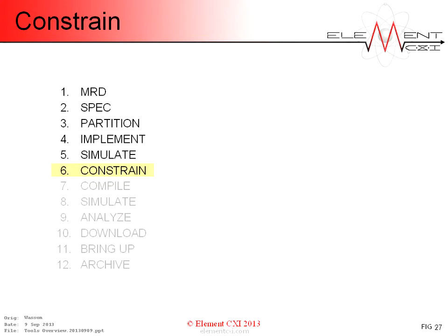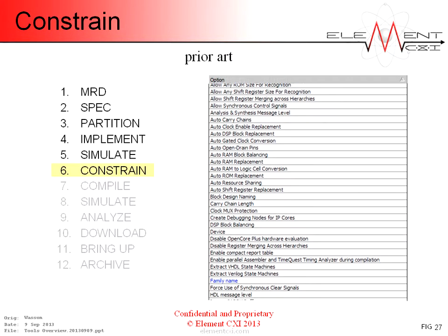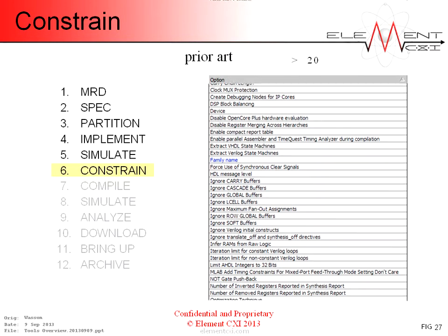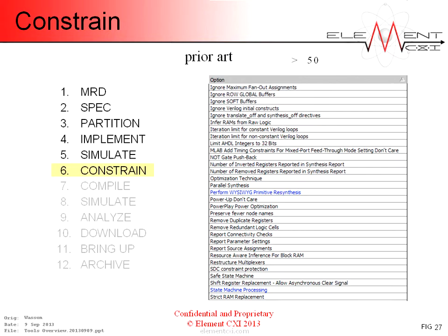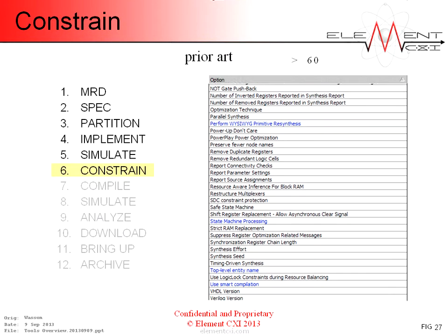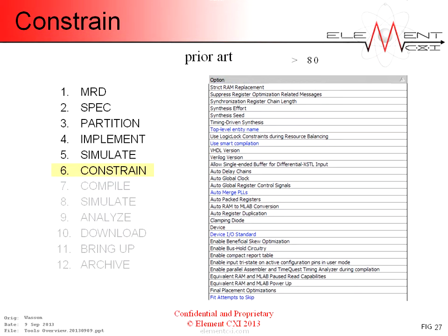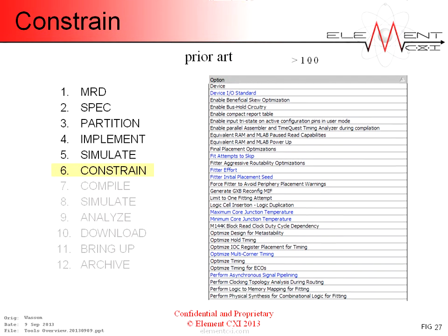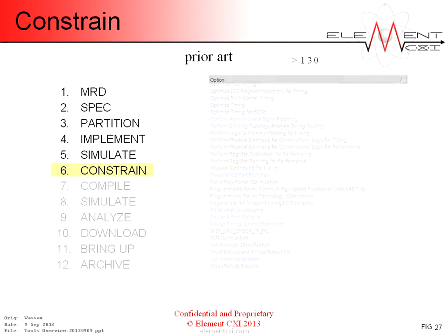Constraints in the real FPGA world have gotten, shall we say, complicated, as this list of Altera constraint options attests. There are options for anything and everything, and things you didn't know you needed options for. There are options for every aspect of compilation, synthesis, analysis, and report generation. Options for effort level settings, resource utilization, netlist optimization, state machine protection, memory equivalence, DSP balancing, register retiming, logic duplication, metastability optimizations, and the ever-popular magic initial placement seed. And this is just one list of constraint options.